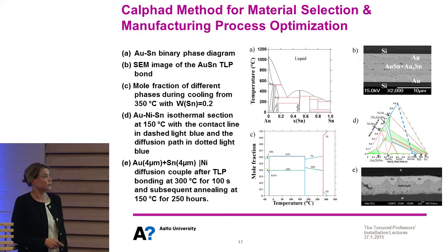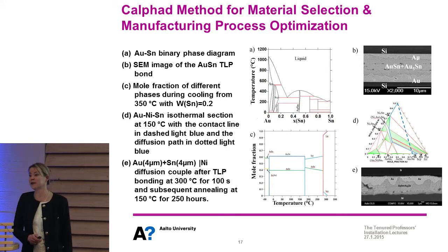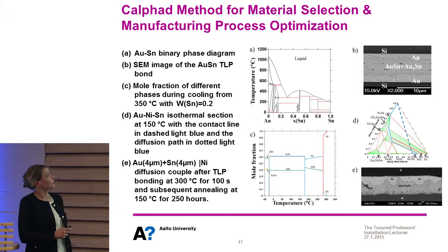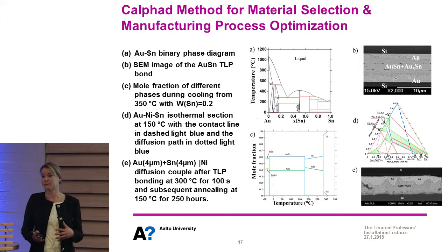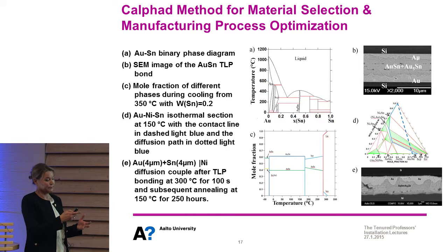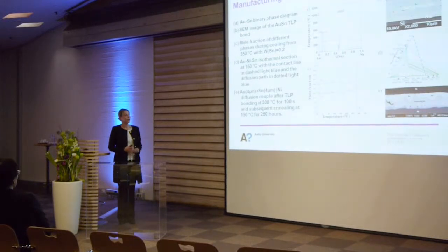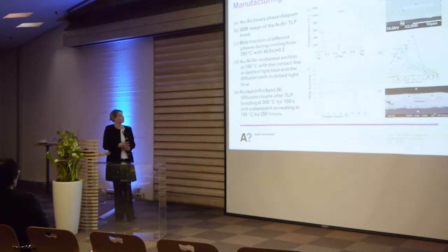So this is just one example of our work in the area where we are developing solid-liquid interdiffusion bonding, which is used in MEMS sensors and also in power devices. By utilizing the Calphad method, the modeling of the chemical reactions, we can find the optimal methodology. We can design the bonding area such that it will be able to take whatever stresses are focused on it, and also keep high reliability over a very long time, over the lifetime.